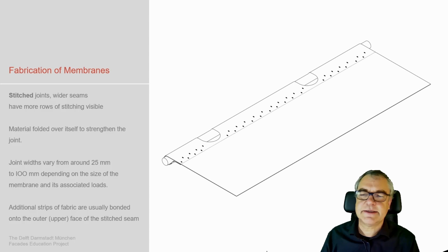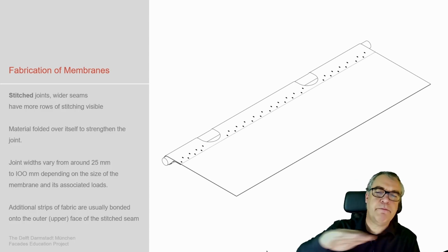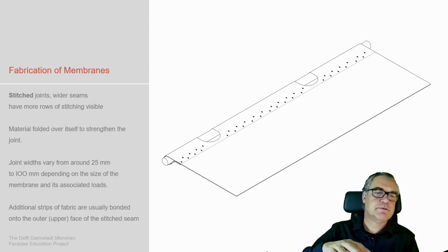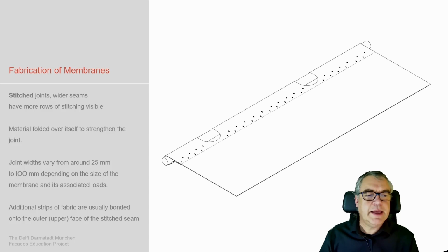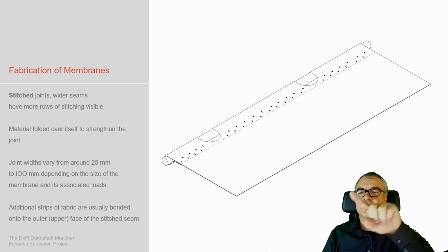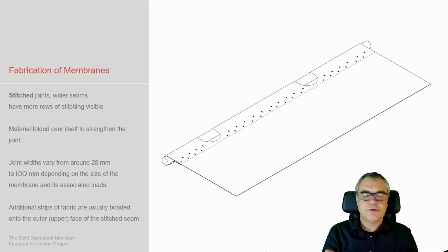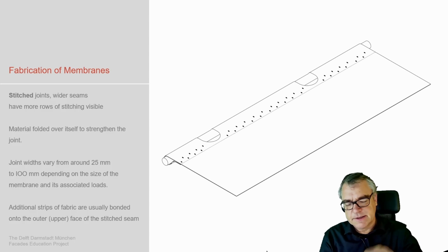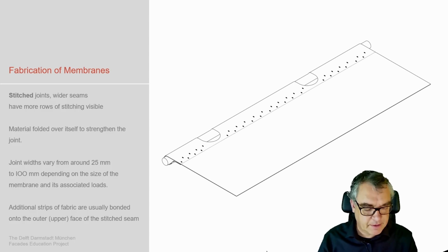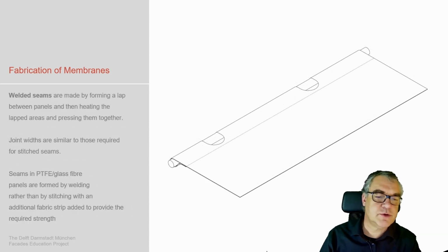How to fix a membrane? You somehow need to get the forces which I talked about earlier into the structure. And the simplest one, as we know this from fabric, is you stitch it. So you see these stitching lines, which means you have an overlap around a certain rope or whatever, and then start stitching the fabric, versus the welding solution.